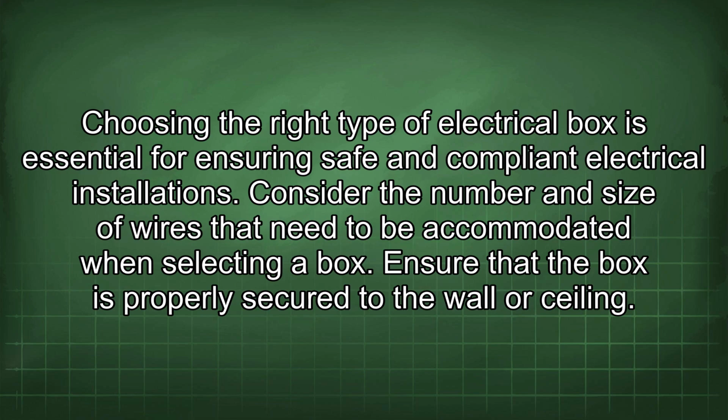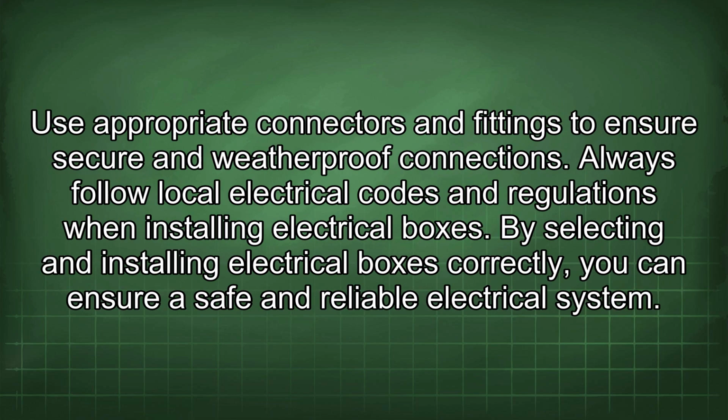Ensure that the box is properly secured to the wall or ceiling. Use appropriate connectors and fittings to ensure secure and weatherproof connections. Always follow local electrical codes and regulations when installing electrical boxes. By selecting and installing electrical boxes correctly, you can ensure a safe and reliable electrical system.